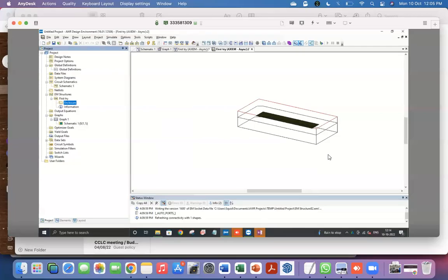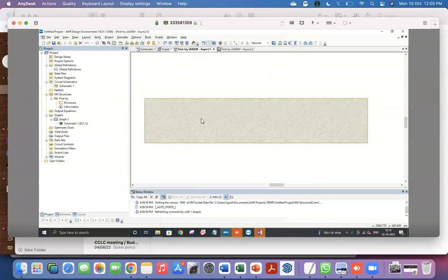So now you have the full thing defined. So we can now set up the actual simulation. And before we do that, we have to add the ports. So this basically tells you it needs to solve, because at the end of the day, the goal is to compute the scattering parameters, like transmission, reflection. So you need to specify the reference where you're doing the excitation from. So this is sort of related to your question.